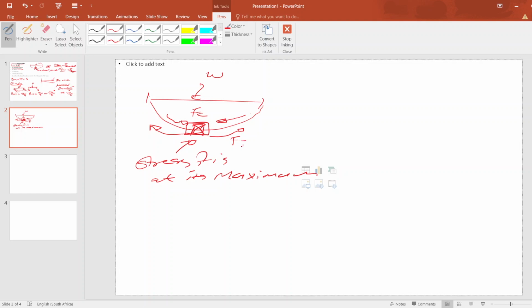It is force tensile. Then we will be using the bending stress graph to determine which stress dominates. Remember, if we are looking for stress compression, it will be force compression over area. Which area? The area of the critical point. Or it will be stress tensile equals force tensile over area. Which area? This area here at the critical point.